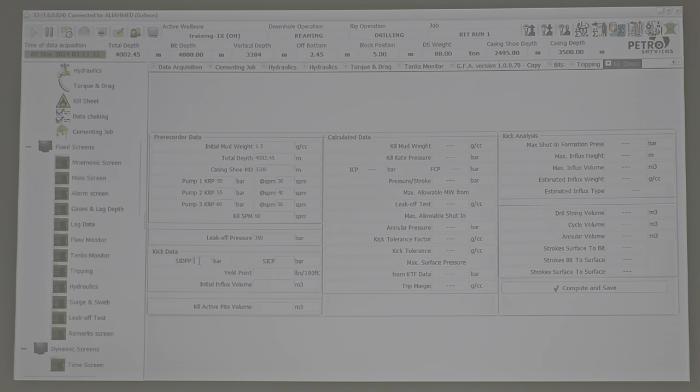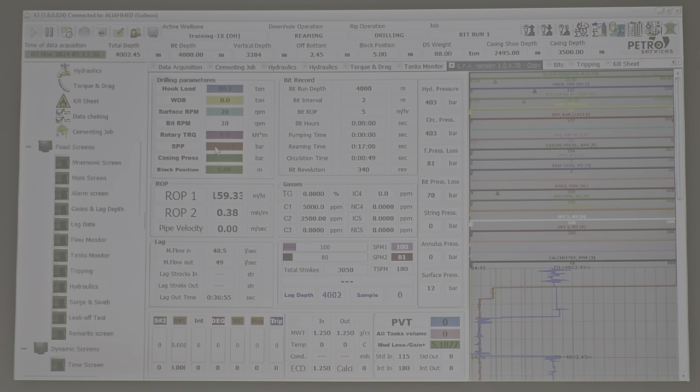It will be on your screen here. Shut-in casing pressure will be on your screen here. So you will find in this situation no pump, they switch off the pump, and the top drive is steady, then this becomes higher, this becomes higher. Now you know that we have a critical situation in the rig. So we have shut-in drill pipe, we have shut-in casing pressure.